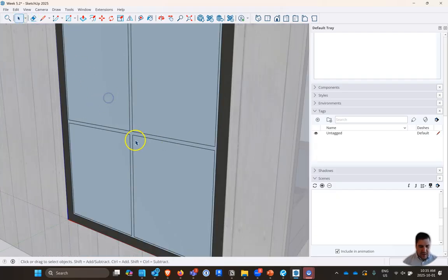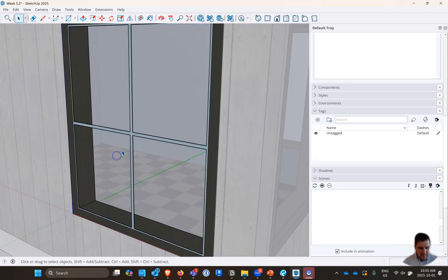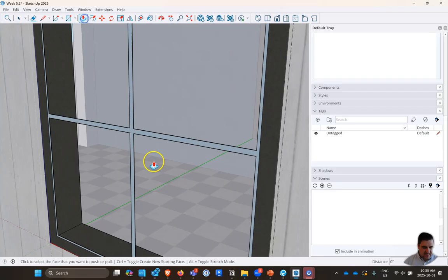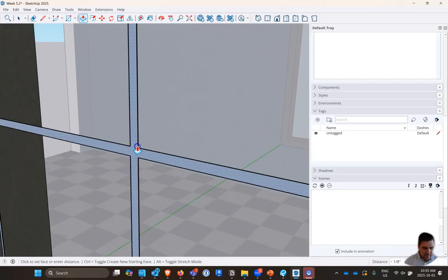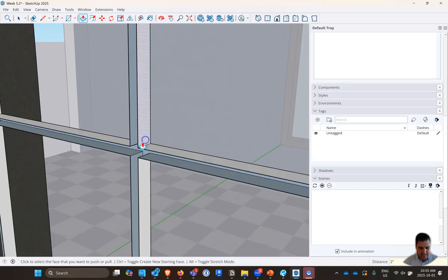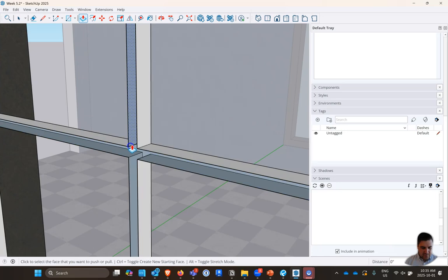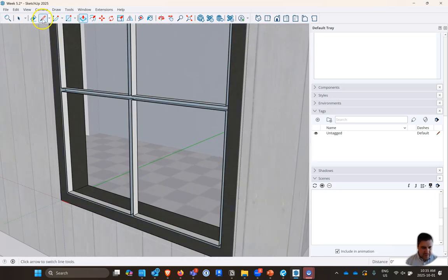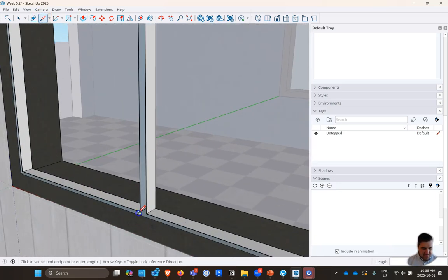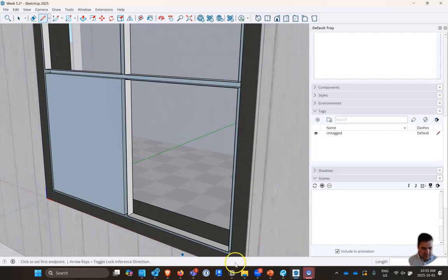But before I do that, I'm going to actually delete these panes here. And we can extrude this middle part in. So let's maybe extrude it in 2 inches. And then again, we can extrude it back out, and it doesn't want to actually work that time. So the cool thing about this too is we can actually just draw one line, and it will fill in that box.